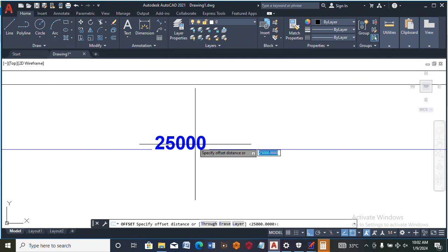There are various criteria governing the height of your truss. You can check your design manual: from span 6 meters to 12, the apex ratio is 4 and 5; from 15 to 30, apex of 7 to 8. So there are so many criteria. Before you carry out any steel work, you must have a good knowledge of your design manual. You put it by the side because you can't do steel design without the design manual. So I'll be using a ratio of 4 to 5 for our span of 25 meters.